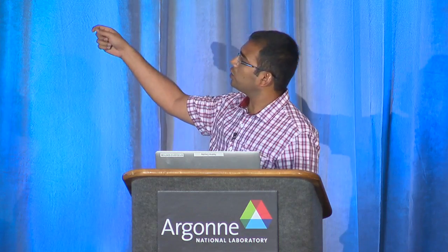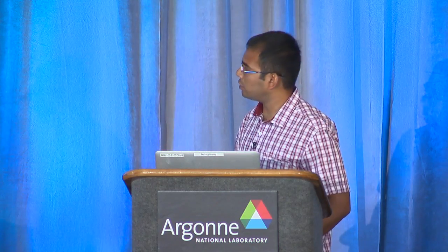You could potentially use the CAD model, if it's available, so that the new vertices introduced in your refinement conform to the actual geometry. Or we also have algorithms that provide surface reconstruction. Basically, utilize the patch surface on the boundary and reconstruct a higher order surface so that you reduce your geometric errors when you refine the mesh.